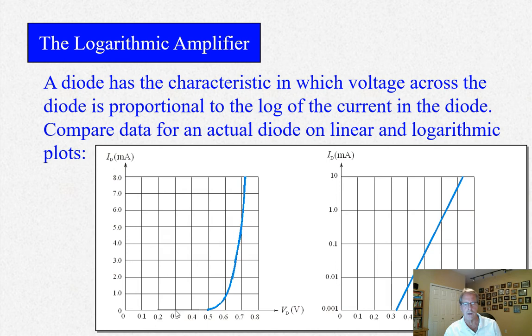So here's the curves. Here's a log curve right here. Okay, so you see it's nonlinear. This is showing the actual current voltage curve of a diode. All right, so this is the real current voltage curve for a diode. As the current for the diode increases, the forward voltage increases, but not as much as the current, in a relative sense. So down here we got this logarithmic characteristic. This one over here is a linear curve. So you see the difference between the two.